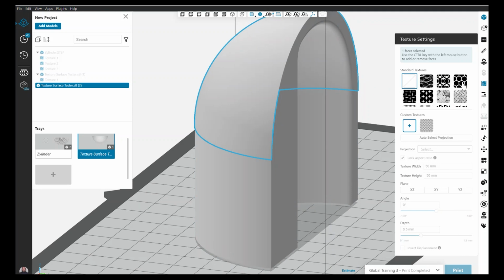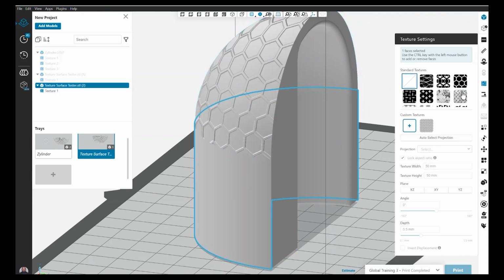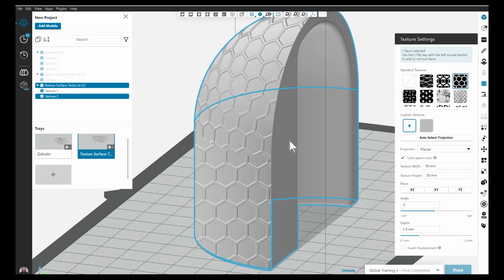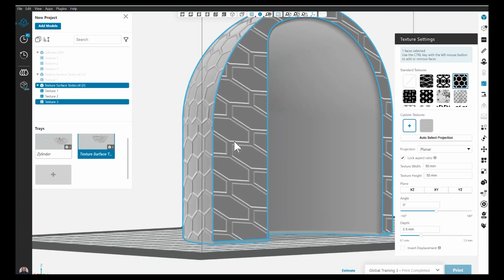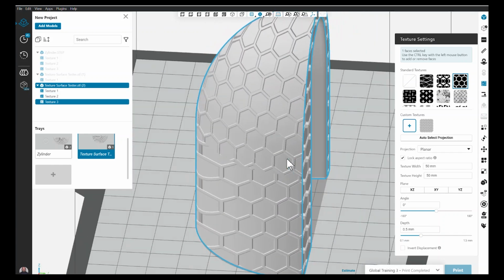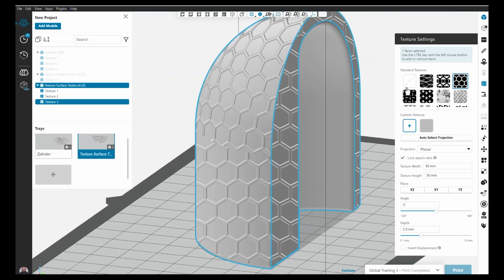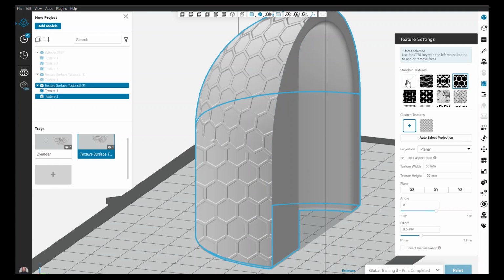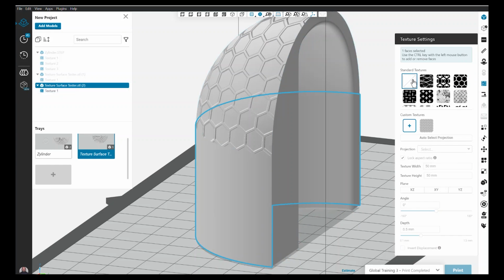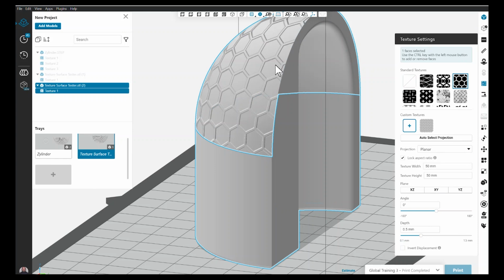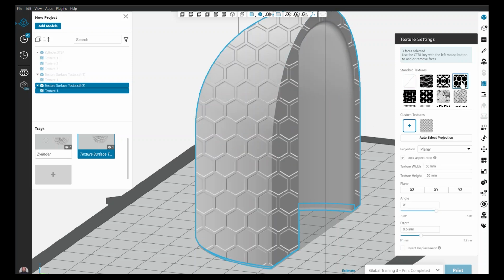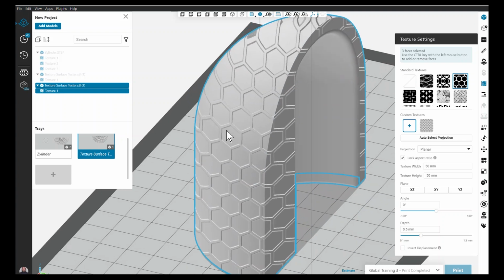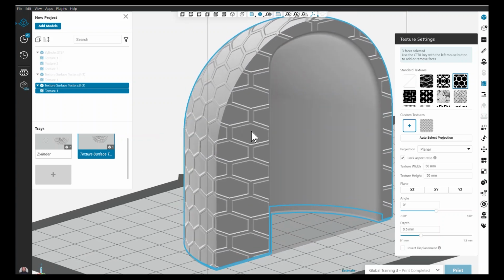To remove an applied texture, select a face and the empty tile in the Texture Tool library. When applying a texture to multiple faces, seams or disruptions can be visual where separate faces meet, providing an unwanted visual effect. To avoid this issue, hold Shift and select multiple faces before applying a texture to allow the pattern to uniformly apply across the selected faces, providing a more uniform pattern.